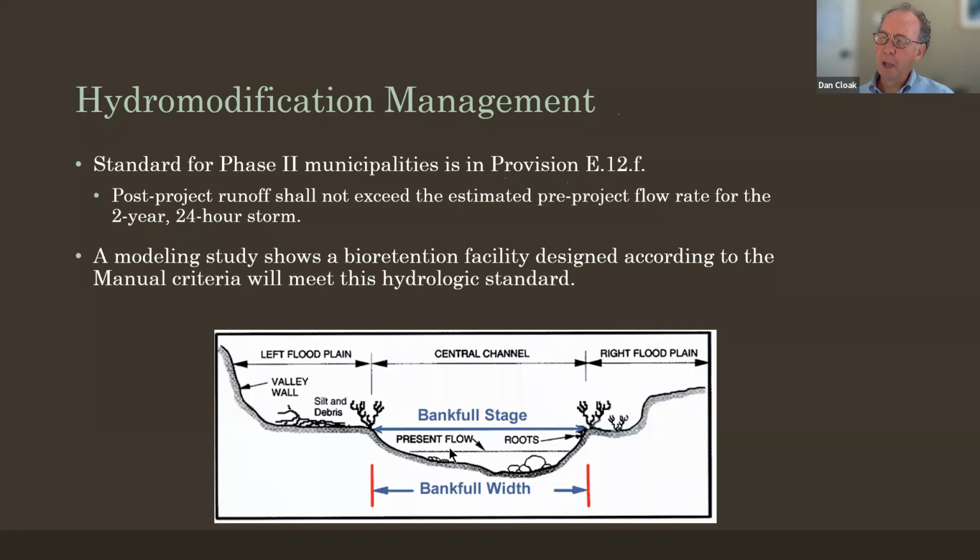If you think about that, that is simply going to increase the duration of flow at this level. And that's what you've accomplished with your detention and release. That, as has been found through studies done over the last 2-3 decades, can actually aggravate the hydromodification management effect and increase stream erosion.